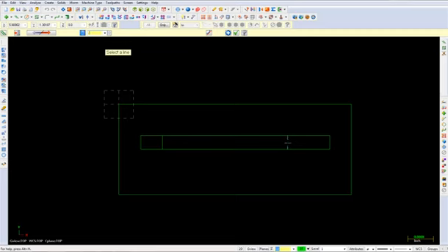Change the offset distance to 0.75 inches. Repeat the same step using an offset distance of 1 inch. Select the Apply button. Choose this line here and a point above it. Enter in the distance 1.1875 divided by 2 and press Enter. Choose the Apply button and repeat these steps for a number of certain values, for the values that I show.